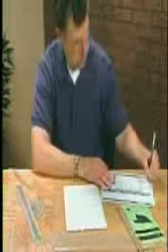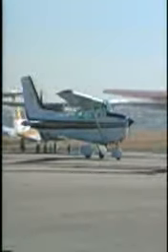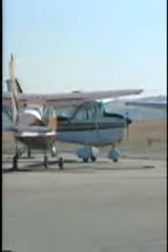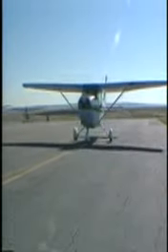Read back all clearances involving active runway crossing, hold short, and taxi into position and hold instructions. If you are unsure of your position, stop and ask for assistance. Tower-controlled airports can offer progressive taxi instructions. Report deteriorating or confusing airport markings, signs, and lighting to the airport operator or FAA officials. Also, report confusing or erroneous airport diagrams and instructions.